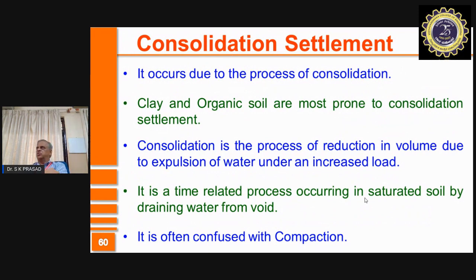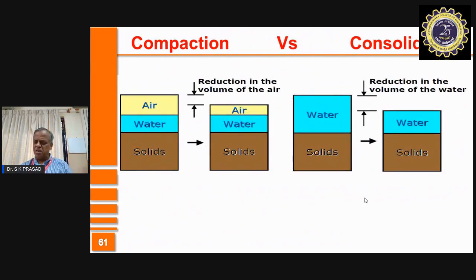Let's now move on to consolidation settlement. And it is due to the process of consolidation. I don't have to explain in detail because my colleague will be talking about this. Remember, consolidation is due to the process of the removal of water from the soil mass. And this removal happens because of the extra load which we apply. And many a times, people confuse with compaction. So I thought I'll very briefly explain the distinction between the two.